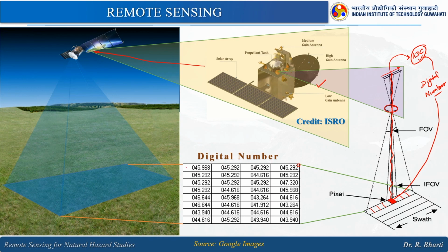The background of this image is your image matrix. These elements are nothing but the digital numbers, the reflected or emitted values captured by your sensor. Now you can understand how remote sensing images are different from our normal camera image, because remote sensing is essentially an instrument based measurement where we have the option to select the appropriate detectors which are sensitive in a particular wavelength range. In a mobile phone we generally use 400 to 700 or 400 to 1000 nanometer.